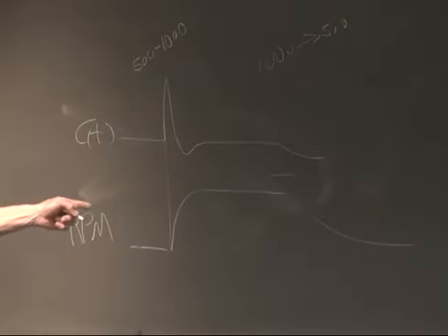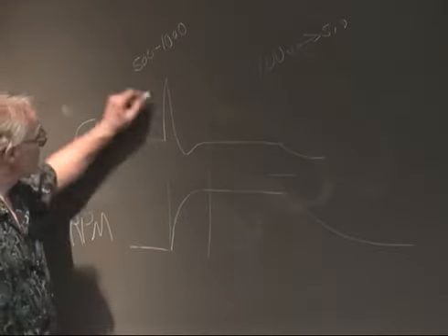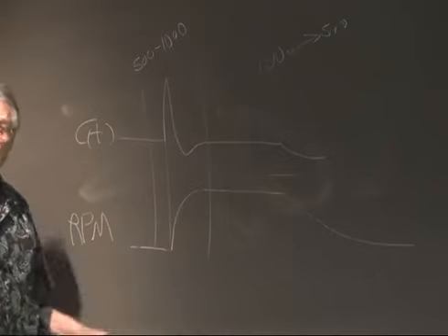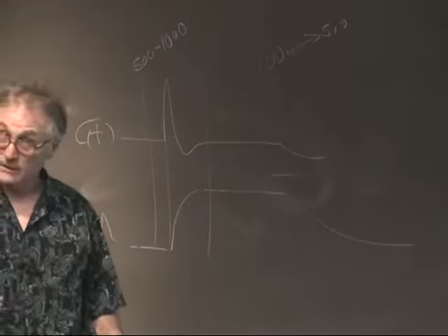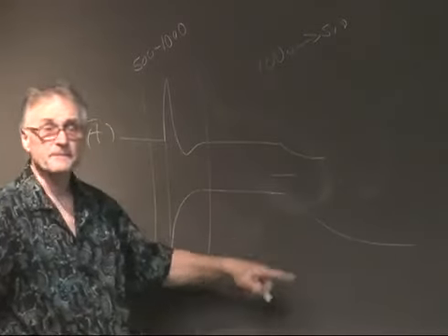You might want to expand out this portion in detail to get the 0 to 80% or 0 to 90% rise time, to document that, since that's one of the things you're going to be graded on. You might want to do 0 to 90% on the falling phase.